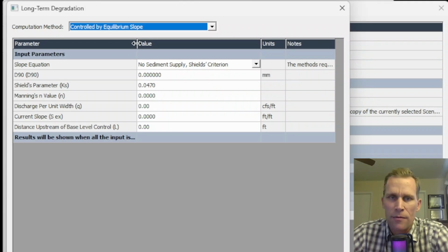When water is released from dams or detention ponds, downstream channels tend to degrade until shear stress is too low to mobilize the bed. In sandbed channels, this can cause significant degradation, but less degradation occurs in gravel bed channels.